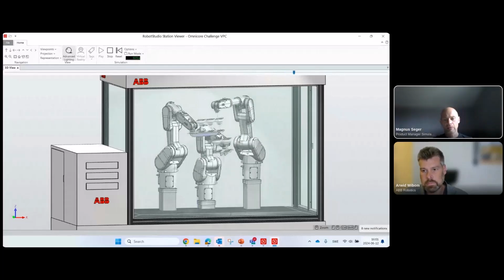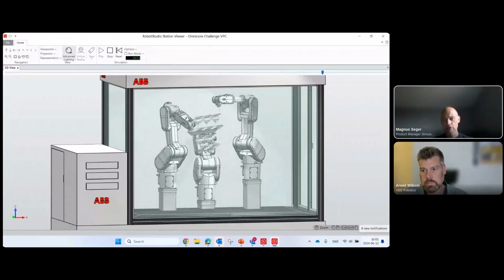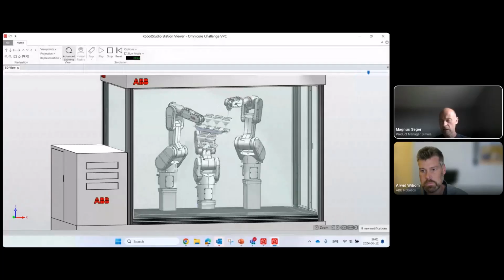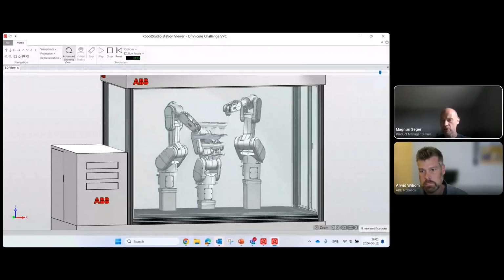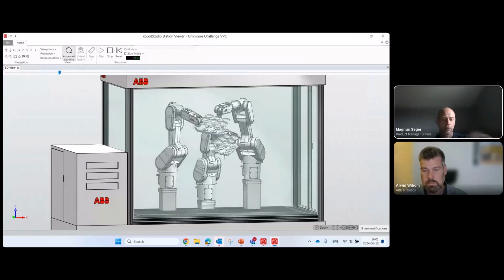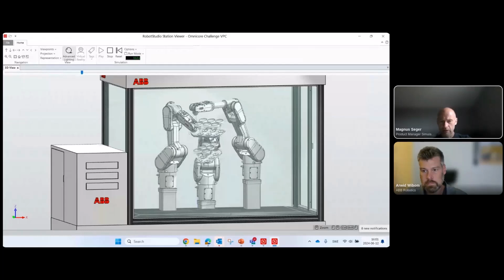I think some of the things that we have shown today help. Usually you have some sort of template setup in a robot program: how you would like to communicate with your PLCs, how that logic and structure is, and also maybe the sequence, how the recipe handling is happening. It really depends if you have those things structured. Those usually give you the skeleton of your robot program, how you communicate and get these orders. So that's one part, the logical way.